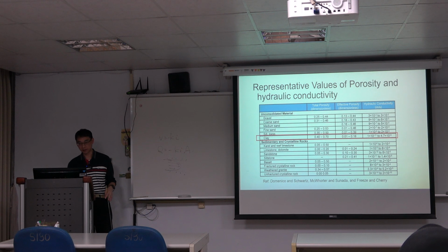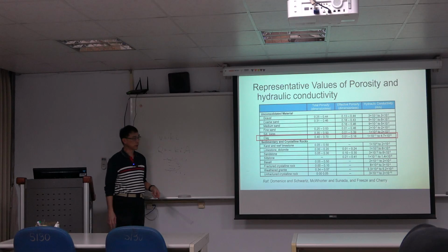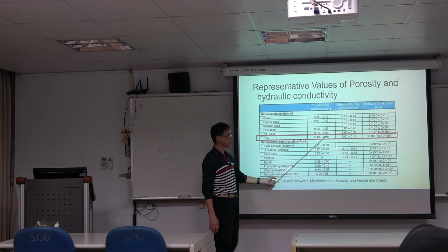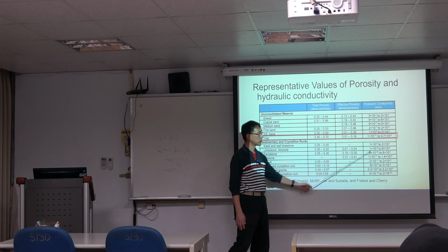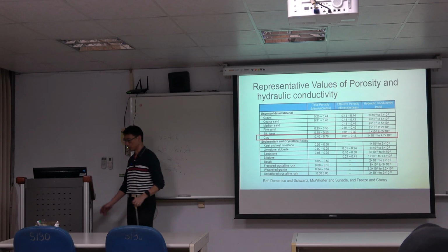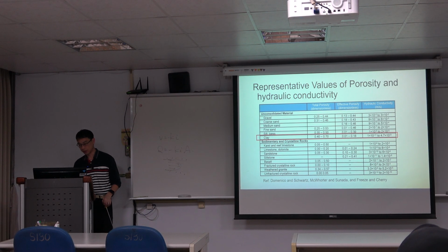And porosity, conductivity, and hydraulic conductivity are also for your reference. We emphasize that clay has high porosity, but very little effective porosity, and then very low hydraulic conductivity. So this is a very important property of clay.